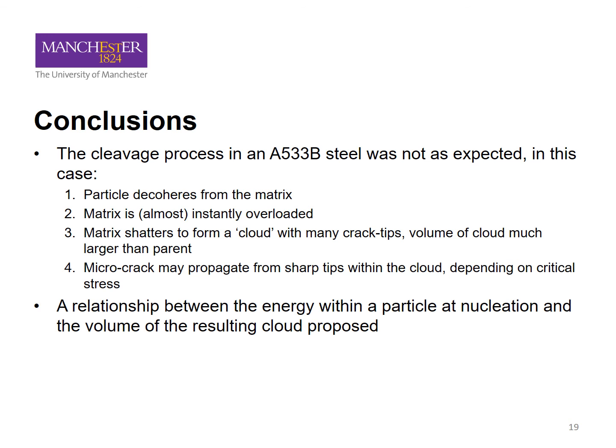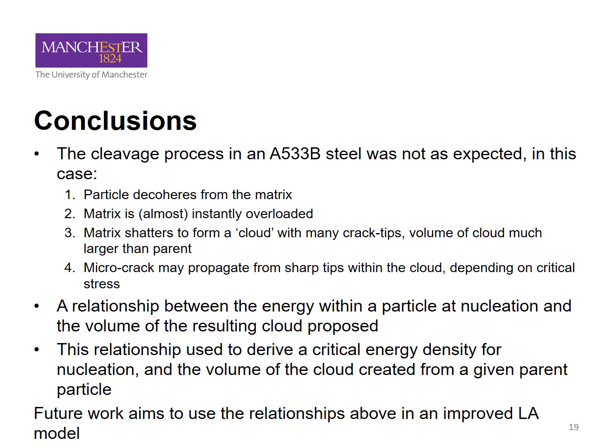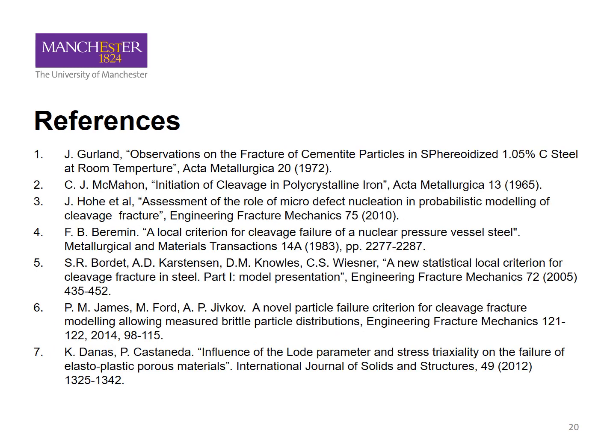A relationship between the energy within a particle at nucleation and the volume of the resulting cloud has been proposed, and this relationship has been used to derive a critical energy density for nucleation and the volume of the cloud created from a given parent particle. Future work aims to use the relationships above in an improved local approach model. And here are some references.